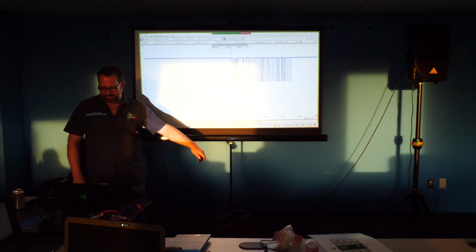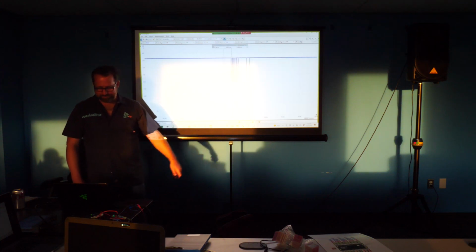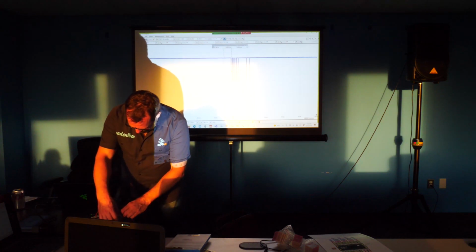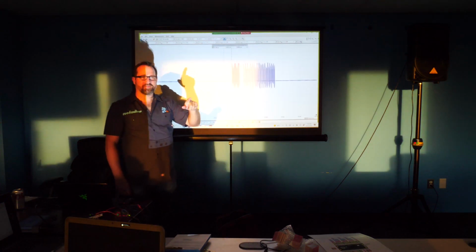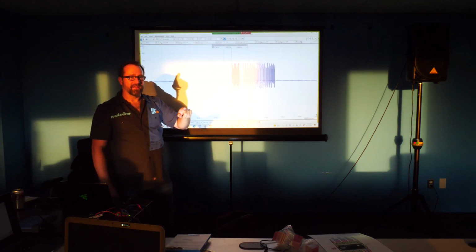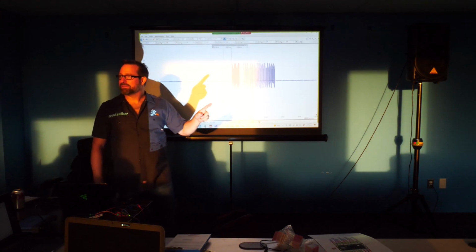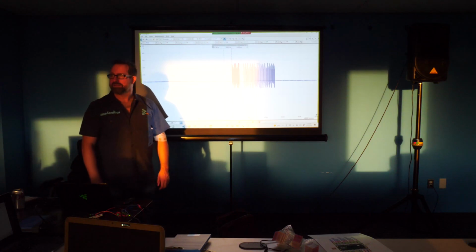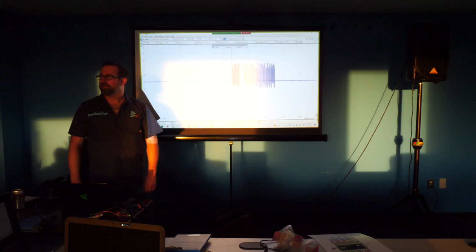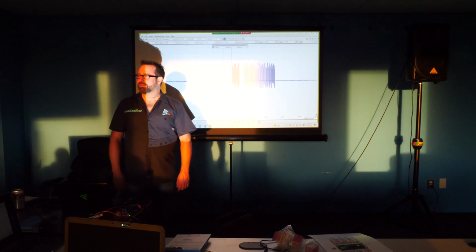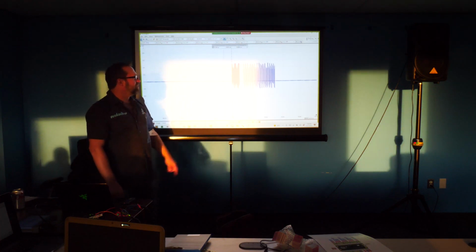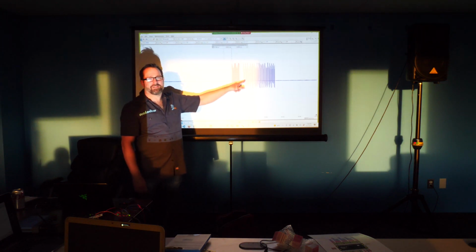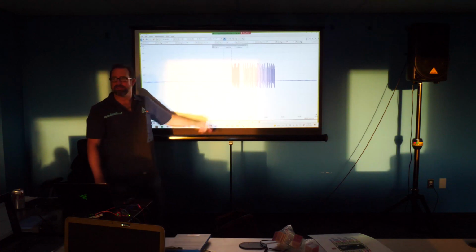Anyway, so that's what that looks like. And then if you connect to the transmit line, all right, so the difference between the receive signal and the transmit signal. Oh, this is what's coming in from the photodiode, yeah, this is the output. What you're seeing there is probably the 120 hertz flicker from the lights. Well, this might be, but why does it look like that, up and down? Does anyone have any idea?